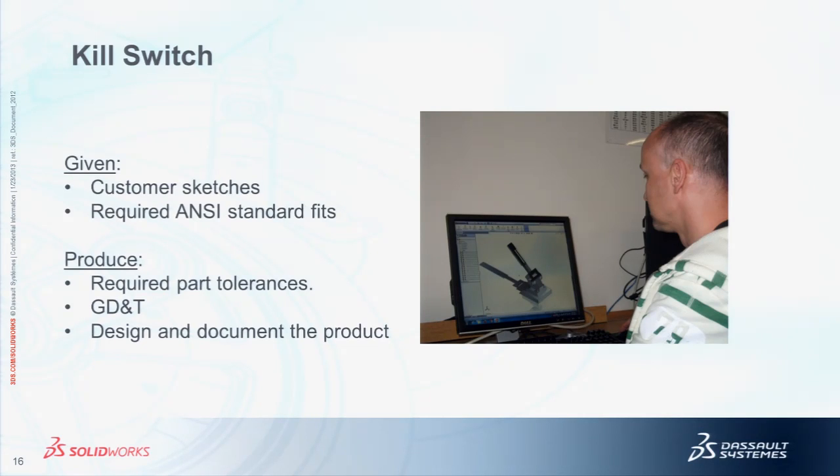Is there anybody using first angle projection? What I do is I just introduce it so they know the difference, and explain that if you get a drawing from overseas or whatever, that's what you're going to look for. So if you open up a drawing and all the views look weird, then think back and think, oh, okay, this must be first angle. Yep, that's pretty much our level of how we cover that as well.